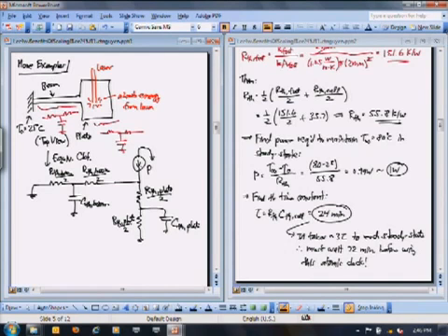Actually, if I want the temperature on the plate, it's going to be right here. That's the temperature of the plate relative to ground, which is T0. Okay, so I'm just going to use this simple circuit to model this whole thing, and that's going to tell me what the temperature is. If I ignore all the capacitors, it'll be steady state. If I include the capacitors with a time constant, then I'll get the time constant. Yes?